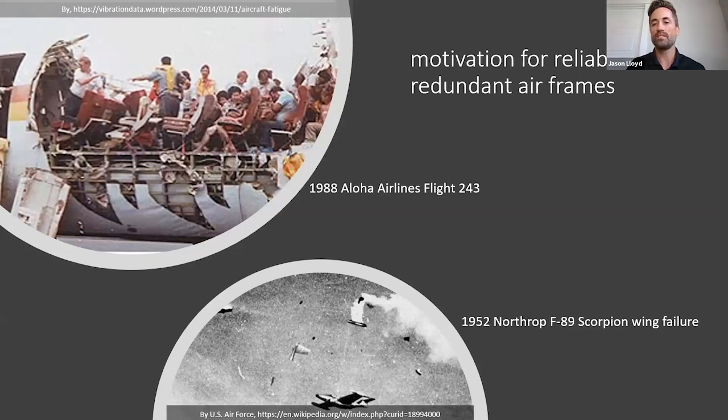Well, the simple answer is that instead of giving up on monoplanes, they developed alternative methods to design, fabricate, inspect, and maintain critical elements of their airframes, exploiting forms of redundancy other than load path redundancy, such as fail-safe and damage-tolerant design methods. These methods recognize that structures must withstand service loads, even when damaged or cracked, until reliable inspection methods can identify that damage.